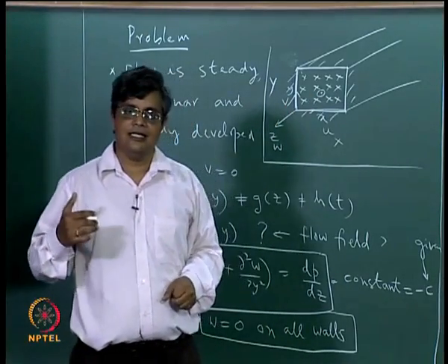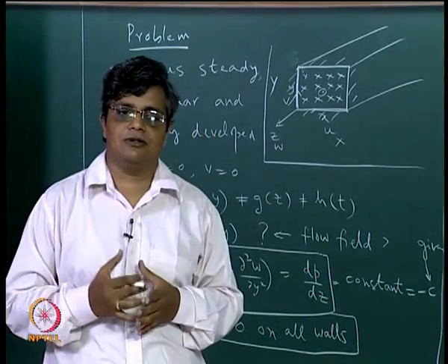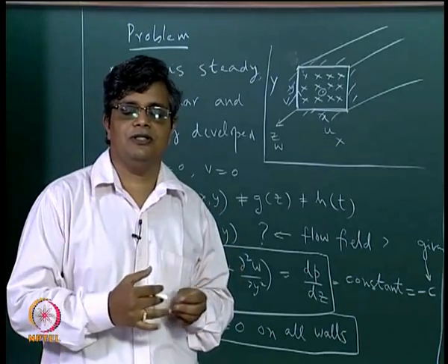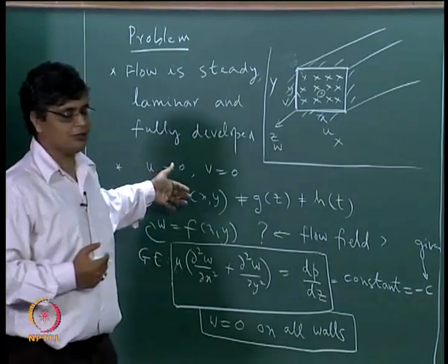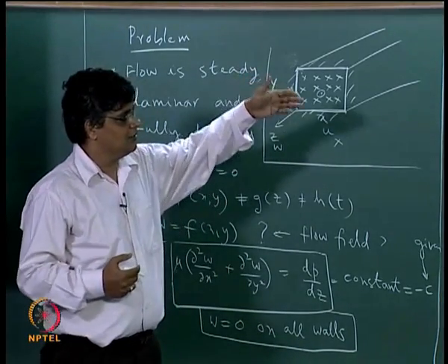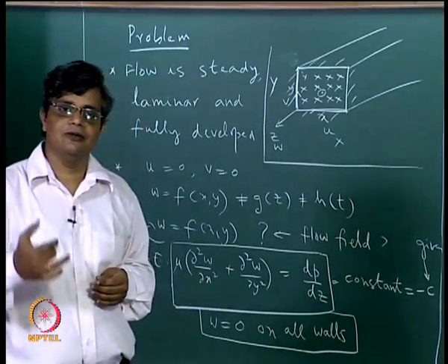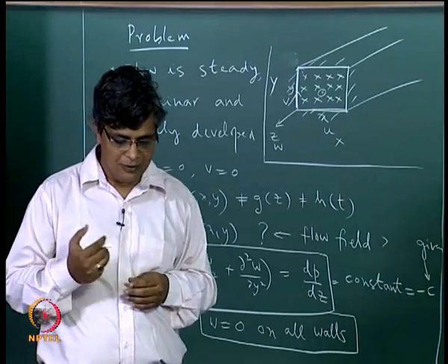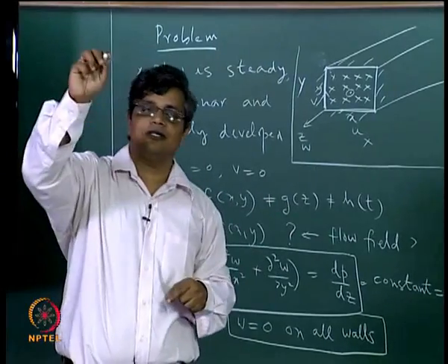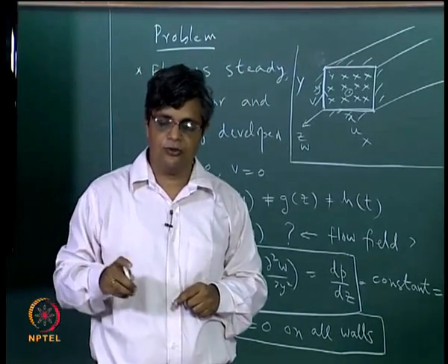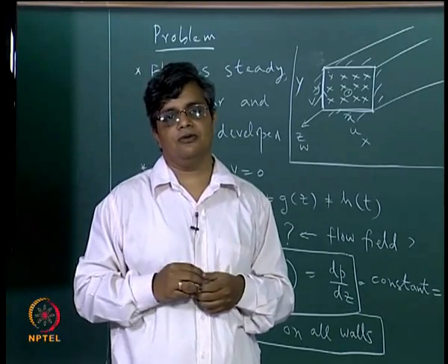So we do not derive the value of a solution at any x and y, we evaluate the value only at specified points which are known as the grid points. And so we are not getting a continuous solution, we are getting a discrete solution, but the points at which we are evaluating are in our control in a way. We decide where to evaluate, but at the same time we don't have total control. For example, we cannot say that in this overall domain I want it at this point and this point. We are forced to have the solution at many points within the overall domain.